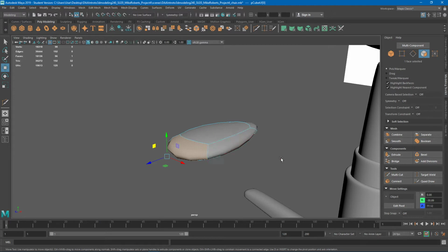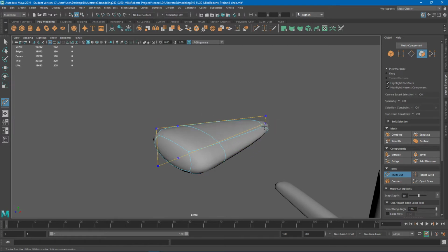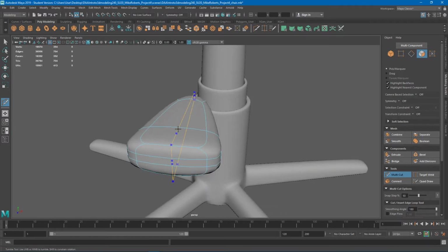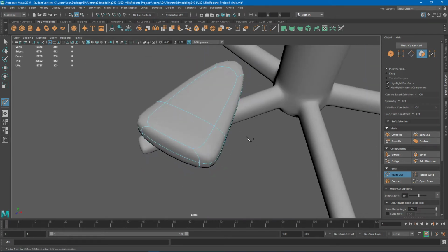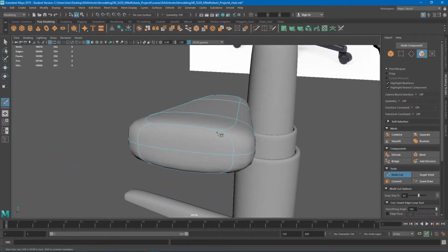And in this case, I can just put in some extra edge loops here, right? Multi-cut, hold down Control, and you notice I'm putting those edge loops kind of close to the corners, right? And that just makes the shape boxy here. Of course, I can hold down Control Shift, which I didn't want in that direction. I wanted one here, right? So see how it can kind of sharpen that shape up?